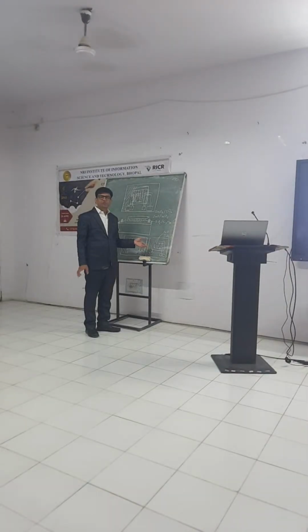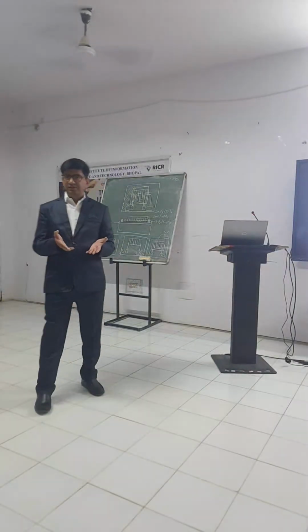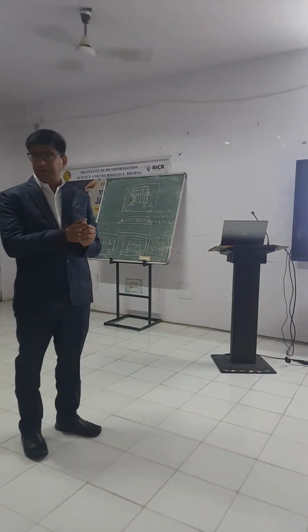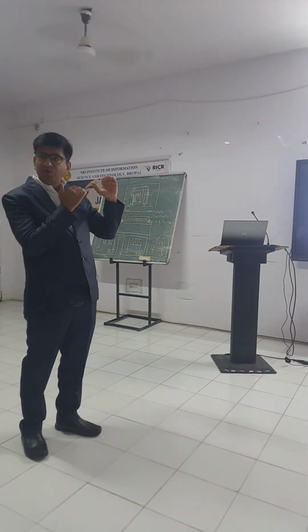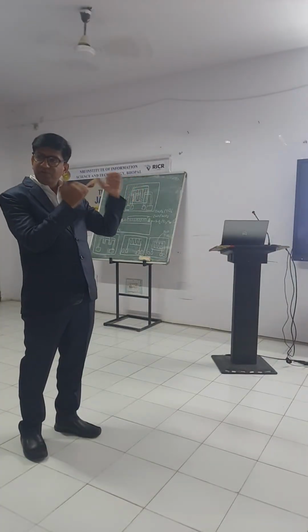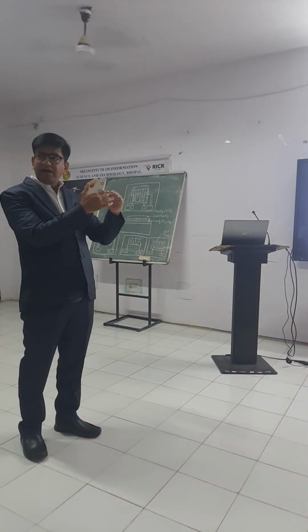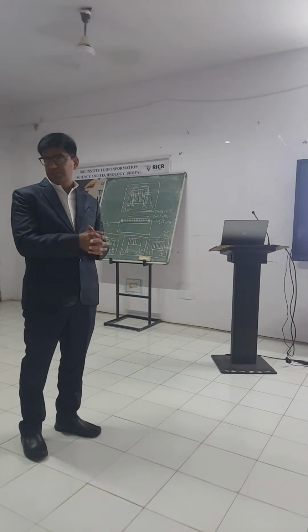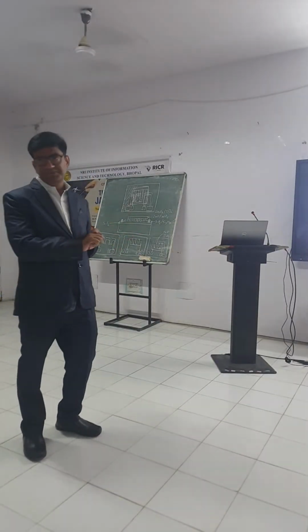So for that, we have to use the lift-off process. In the lift-off process, we just reverse the fabrication steps. Instead of depositing the layer first, we first coat the PR, then do the lithography, then deposit the sensing layer, and after that we go for the lift-off process. Understood? Like that we finish our fabrication process.